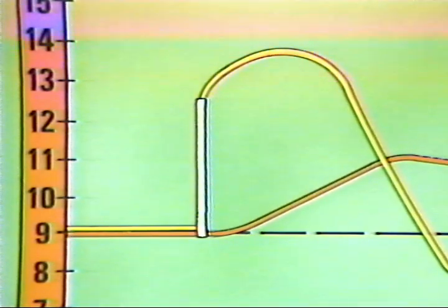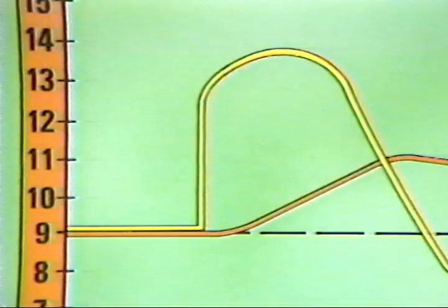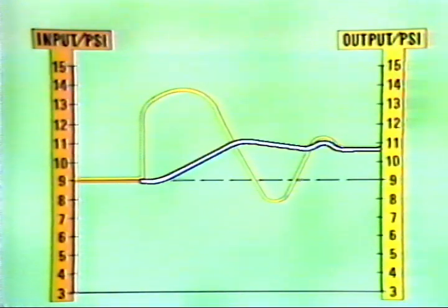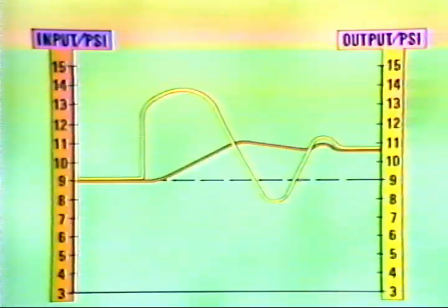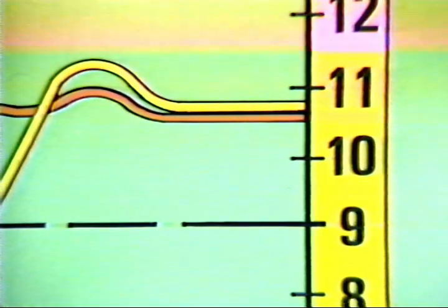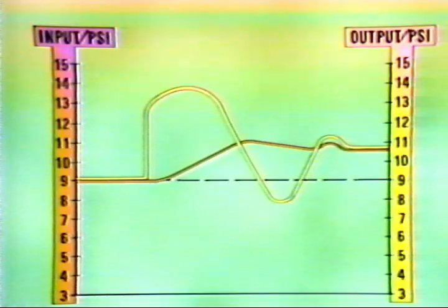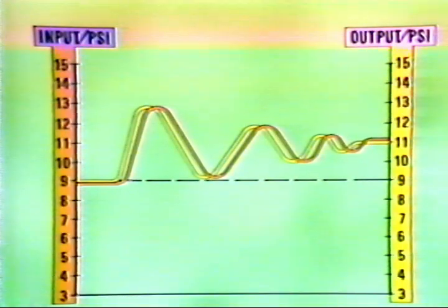A rate controller advances the amount of output based on the expected rate of deviation in a given period of time. As you can see, the process variable settled out quicker than it did with reset control. But as with P-only control, there is offset. It would seem then that the most ideal controller would combine the best features of rate, reset, and P-only control.